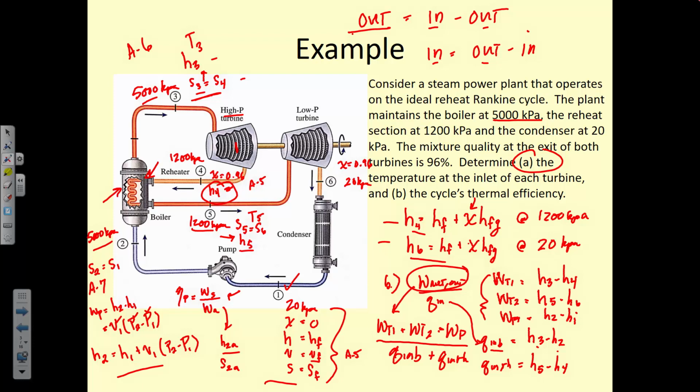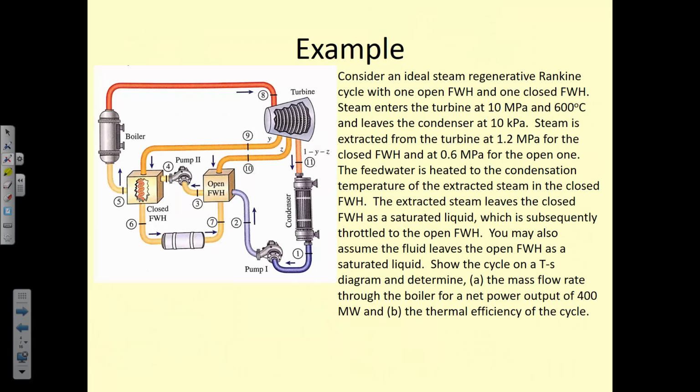On a few examples, on the low pressure turbine section, we would have a thing where it'd be like y, then 1 minus y. You only do that if it's clarified to do that? Well, that's only when there's more than one outlet of a turbine. Like, this is an inlet. It's not an outlet, right? You remember that was when it had the other heat exchanger thing? So when there's a problem like this, you mean? Yeah. Okay, that's when you have 2 outlets.